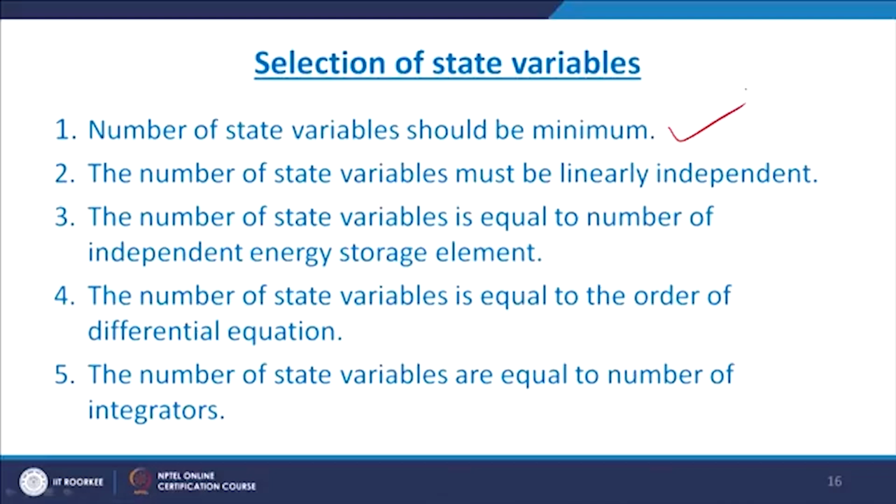The general logic given here to select the state is that we have to select the state which has energy storage elements. Whenever a problem comes to you, you have to see how many energy storage elements are there. Number of energy storage elements equals number of states. So the first point is that the number of state variables should be minimum. The state variables must be linearly independent.